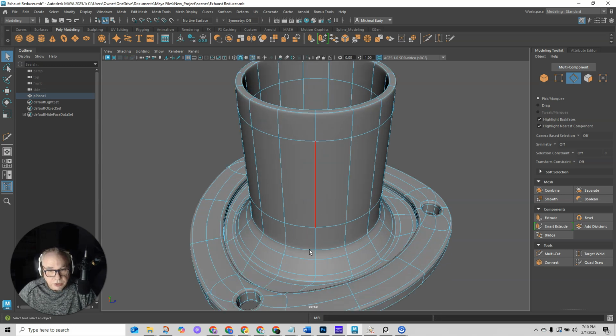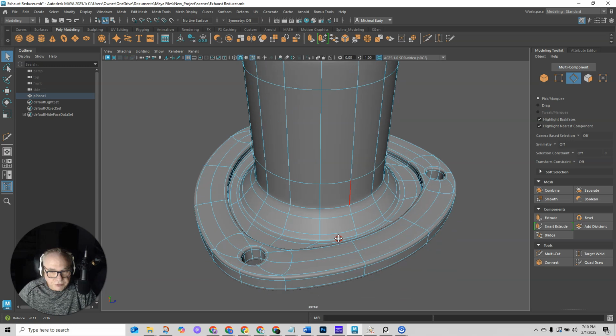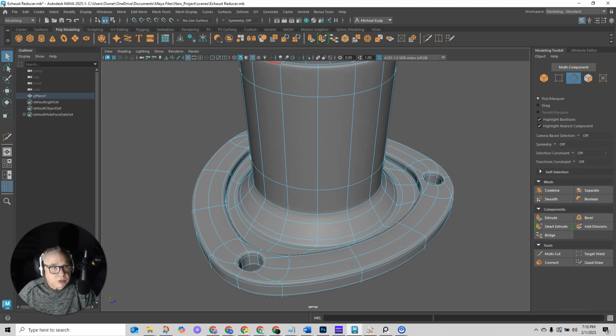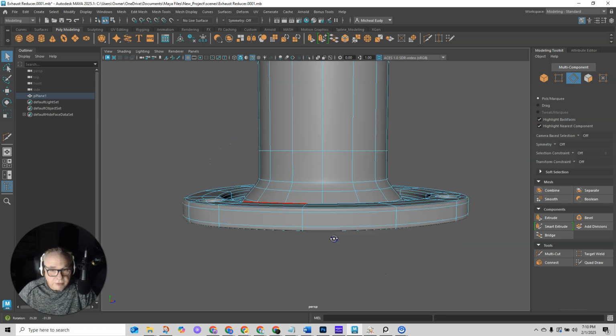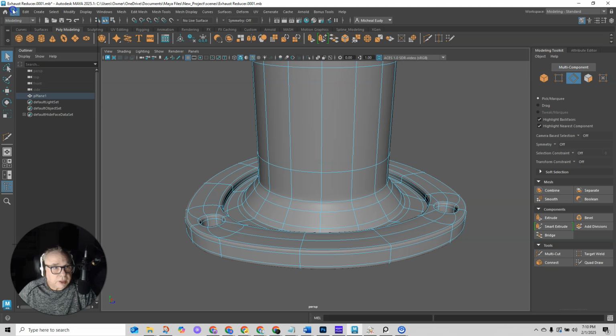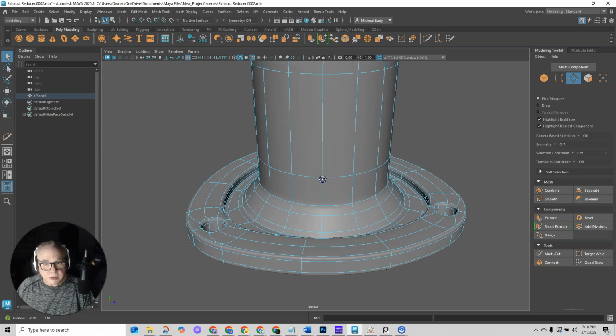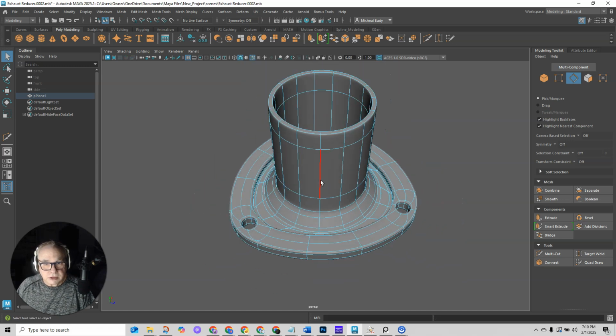And about every 15 minutes or so, you should be coming in here and going incremental save, and then it'll save it again with a new number. And then about every another 15 minutes, you're going to go up here again and say incremental save. And so it's going to save you in stages. That way, when and if this crashes or freezes up or something, you haven't lost everything, you just lost since your last save.